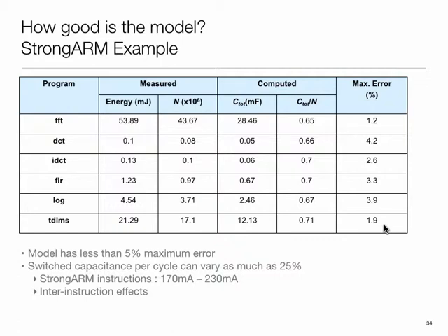So it goes to show that you don't have to do energy accounting on a per transistor level. You can basically take this complicated processor and reduce its energy to a very simple 5-parameter model, or possibly even lower. So ideally, when we are trying to do energy management, you want to create a model which is a lower order model.